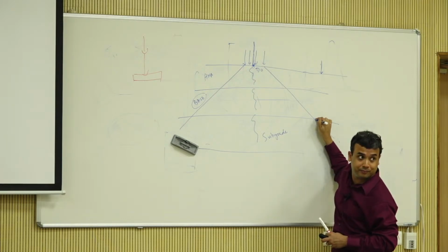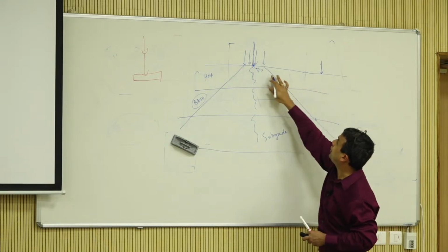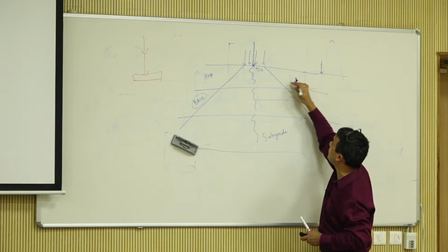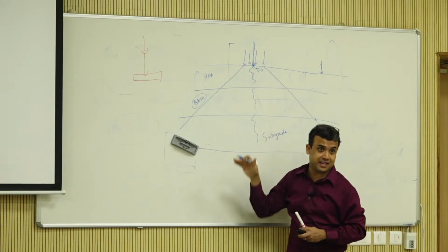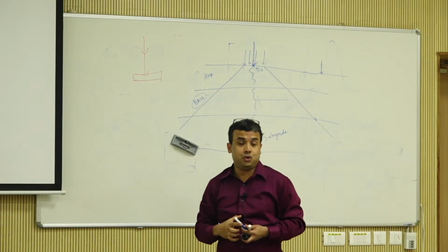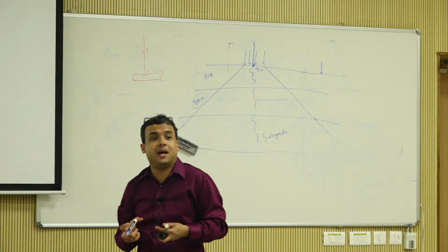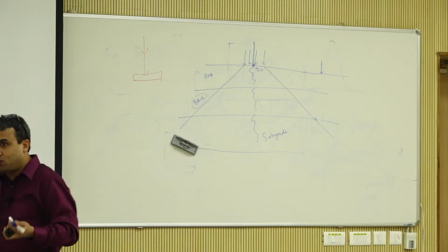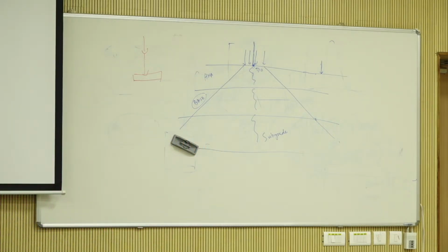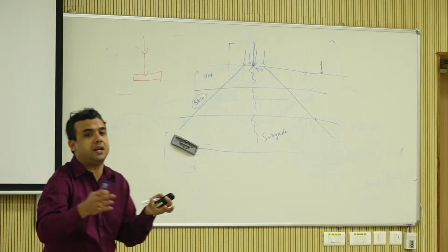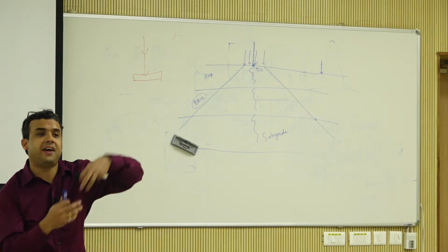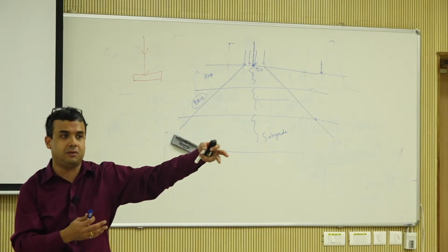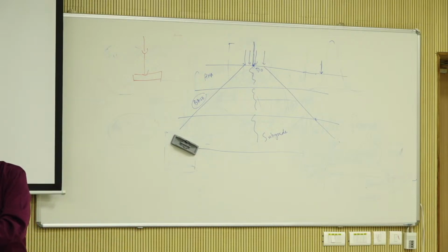Only the bottom, because the top is not feeling any stress here because the dissipation has happened. You use that concept when you are trying to calculate your modulus values for layers, which is called back calculation. We'll get into that in a second, right? The whole idea is, as you move away from the load application point, the layer that affects the deflection or the behavior is going down, down, down.